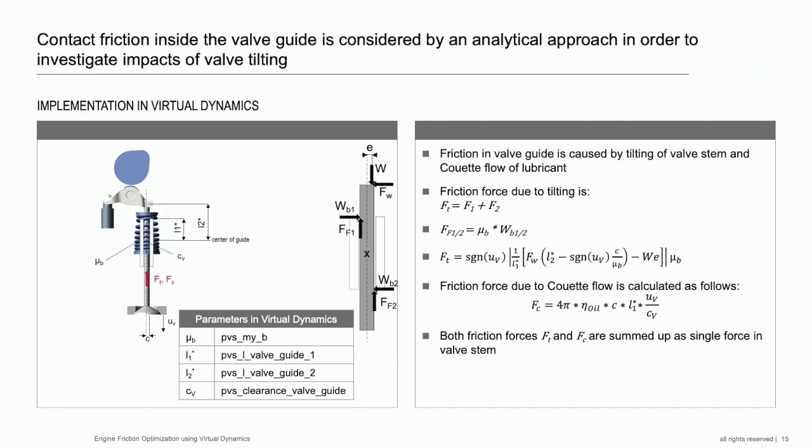Regarding the analytical approach on how to estimate friction between valve and valve guide, we have put up an analytical way to calculate the friction. On the top side, there is a sliding motion between the roller finger follower and the valve, and there is a sliding velocity causing some tilting torque onto the valve stem. Further, the contact has a certain eccentricity, and the normal force is acting on the valve stem end, imposing another contribution to the total valve torque.